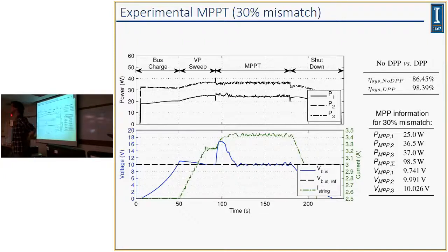So you just need information, or you need to actually adjust the way that the centralized inverter does its control? If you just add an external measurement device that sort of replicates the measurement communication of the centralized inverter, I think you can do that. Really, all you need is that the central inverter gets the bus voltage, and the DPP gets the string current. So it's just 2 lines.